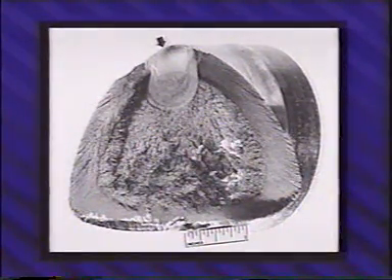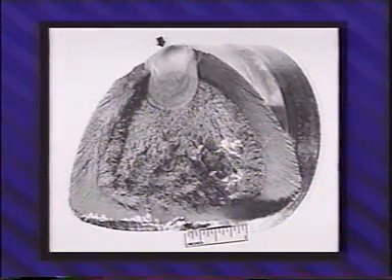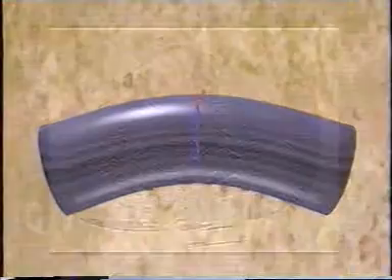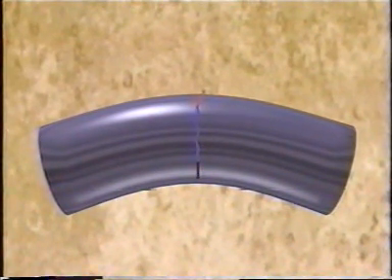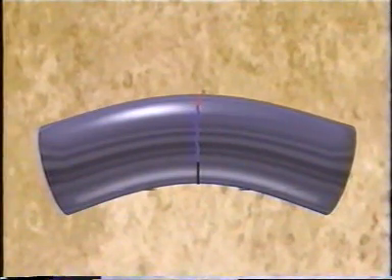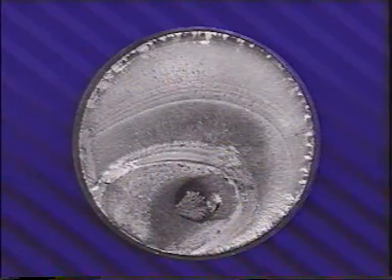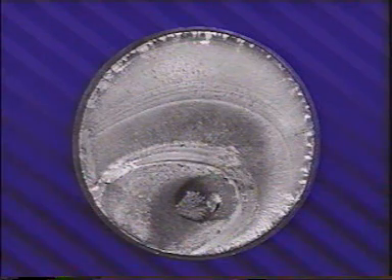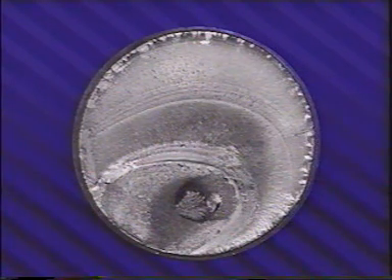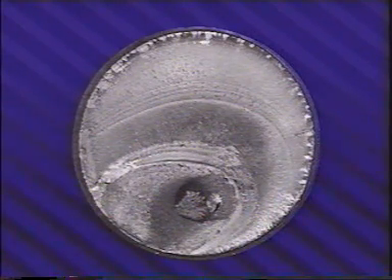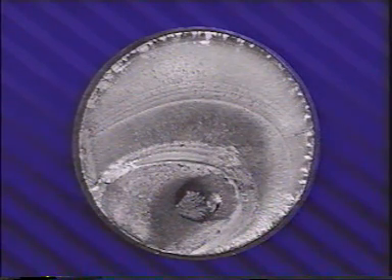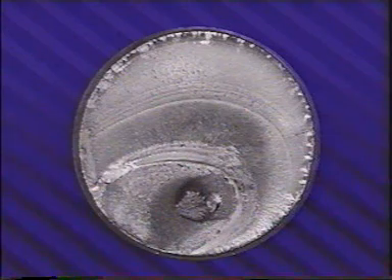This fracture is at a 45-degree angle to the shaft axis, typical of the fatigue and brittle fractures of shafts in torsion. When a crack has grown to the size at which it significantly reduces the load-carrying capacity of the part, a change in the direction of crack growth usually follows. In many parts, the fracture may, in general, still appear flat, but if the level of operating stress is low, the surface appearance becomes rougher and more fibrous. This indicates the change from crack extension to the final fast fracture.